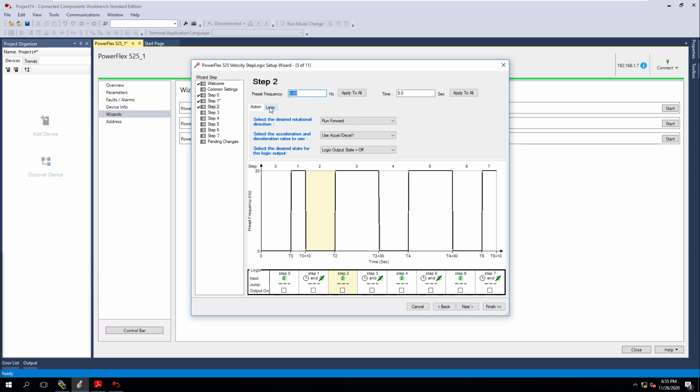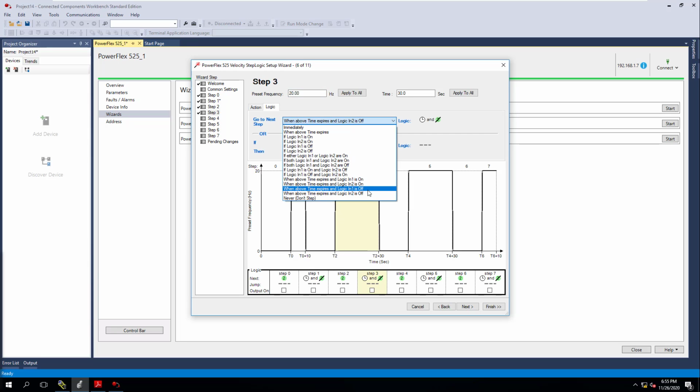Then over here on the very next step, which is the time frame that the operator would be adding the ingredients in the system, it would be the next step, and that's saying, okay, now after the ingredients have been set, the operator pushes the button again, then it would change to the next step, which would be step 3. Then it would run the batch for the set time with the push button not pushed, right?